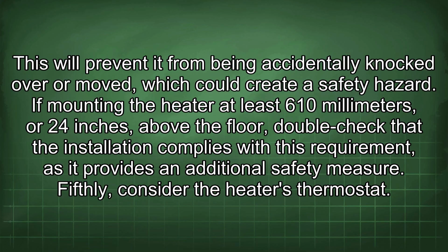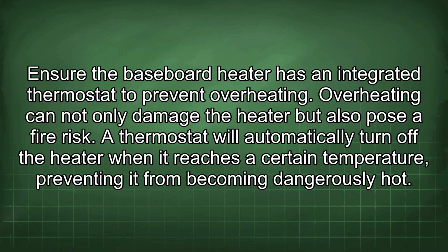Fifthly, consider the heater's thermostat. Ensure the baseboard heater has an integrated thermostat to prevent overheating. Overheating can not only damage the heater but also pose a fire risk. A thermostat will automatically turn off the heater when it reaches a certain temperature, preventing it from becoming dangerously hot.